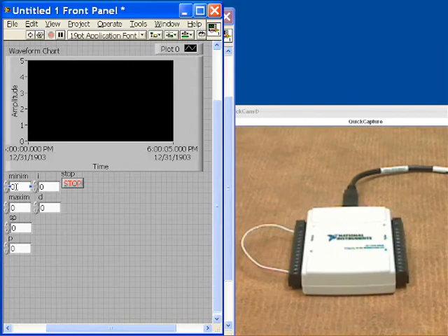The one thing that I do want to set: my minimum is 0 and that's fine, but I want my maximum value to go up to 5. So that's going to limit what my PID can set as ranges or values. Next we want to go and set the P, I, and D values, and we'll set them at some numbers. We'll choose 0.1 for P, 0.1 for I, and then 0.01 for D. And those are numbers I just derived by knowing a little bit about this setup.